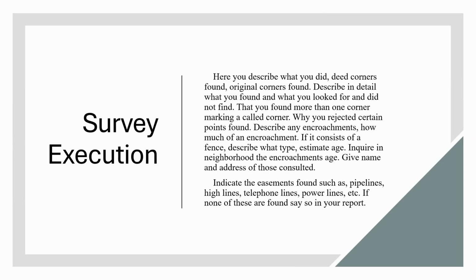If you found things that were in the ground, maybe potentially called for, and other stuff, if you rejected it, why? If you identified mathematical errors or retracement errors on previous retracements, and then you found where they set their points, why did you reject it? If you identify a pin cushion, which piece of monumentation did you use, and why did you reject the other ones? Those are all going to be relevant here at this point.